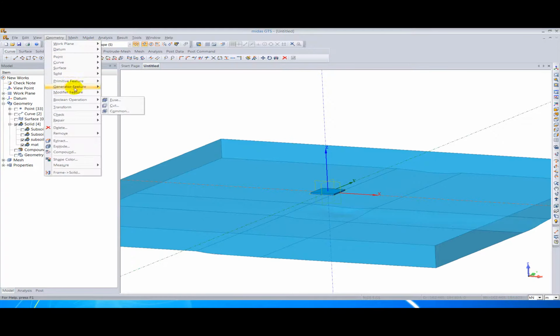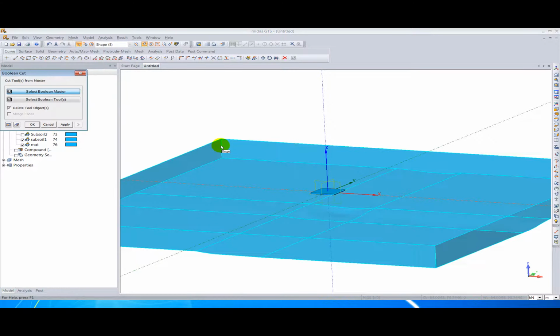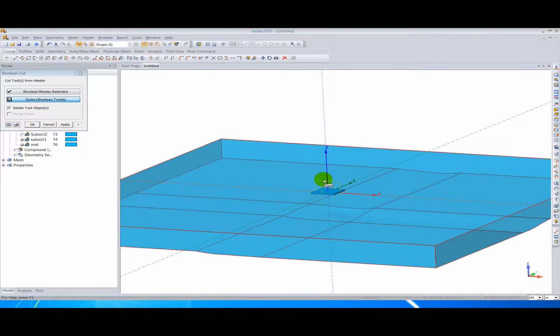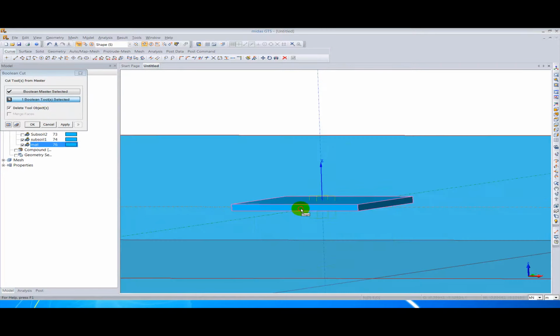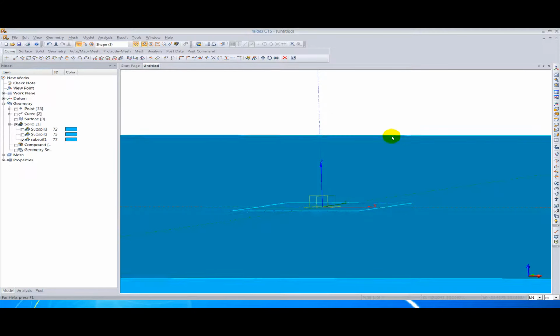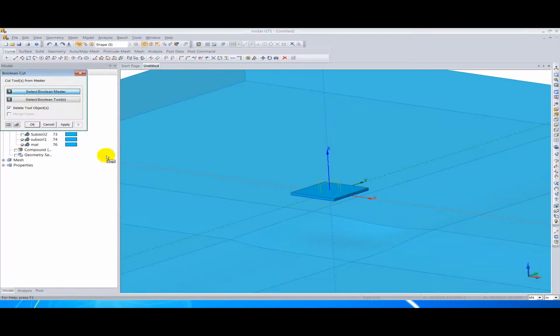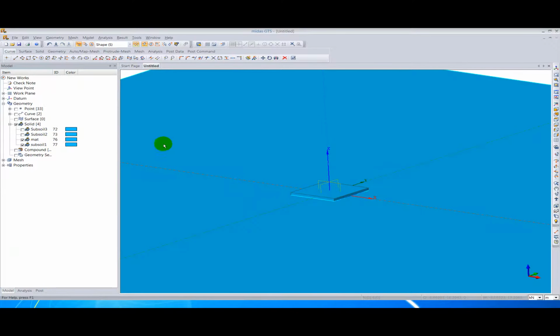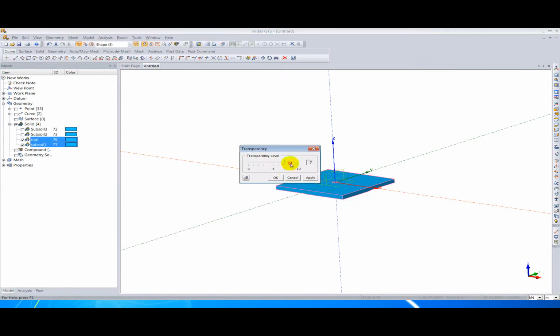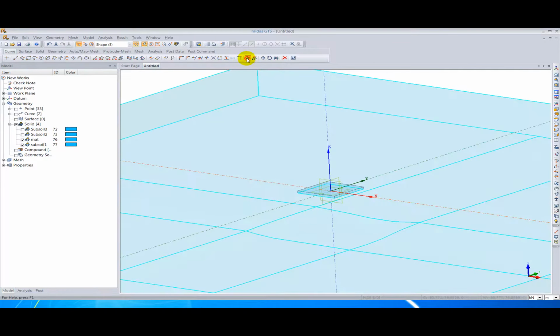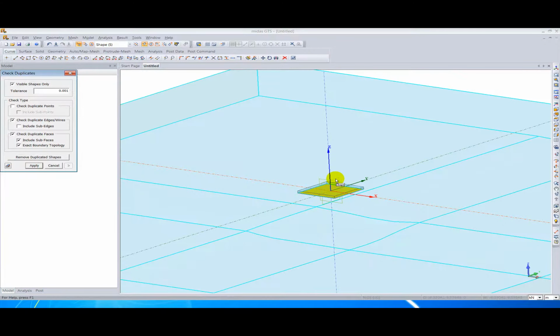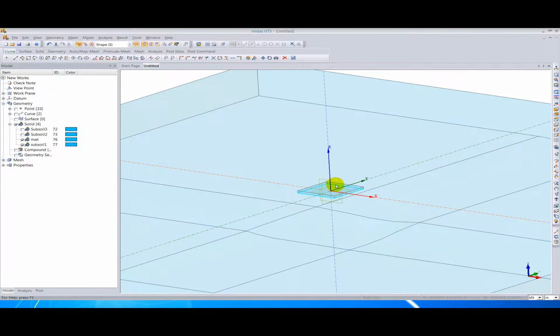So I'll use the Boolean cut feature to do this, and I'm going to use this subsoil 1 as the master, and I'm going to use the mat as the tool. I'm not going to delete any objects. I just want to cut in a virtual surface between these two objects. Did I uncheck that? I better do that again. Boolean cut, master, and tool. I don't want to delete that. And now if I control transparency again, you notice all the solids have been regenerated, and we can see that the relationship between the mat and the subsoil 1 layer has been introduced.